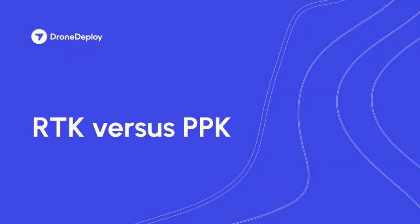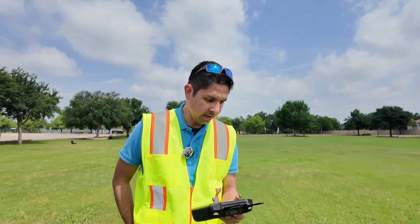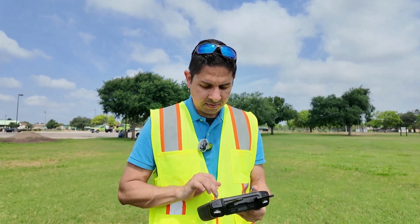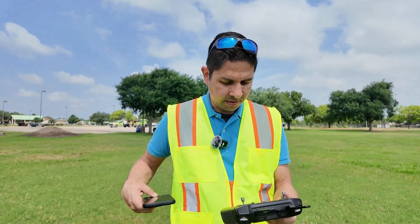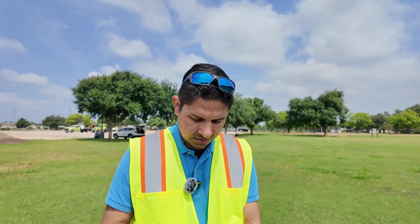So we're getting ready to fly our Mavic 3 Enterprise. The very first thing that I do is to connect to a hotspot again, and that's because I'm going to be opening DroneDeploy and we want to get RTK signal. So I just connected it to the hotspot by swiping down, clicking into the Wi-Fi area. I'm looking for my hotspot. Right there is connected, so we got good signal.